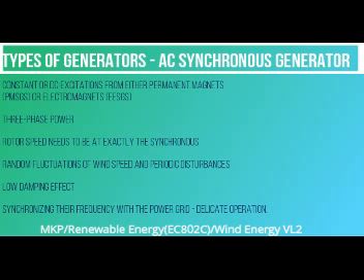In case of fixed speed synchronous generators, the rotor speed needs to be at exactly the synchronous speed, or else synchronization will be lost. When using fixed speed synchronous generators, random fluctuations of wind speed and periodic disturbances happen due to the tower shading effects.